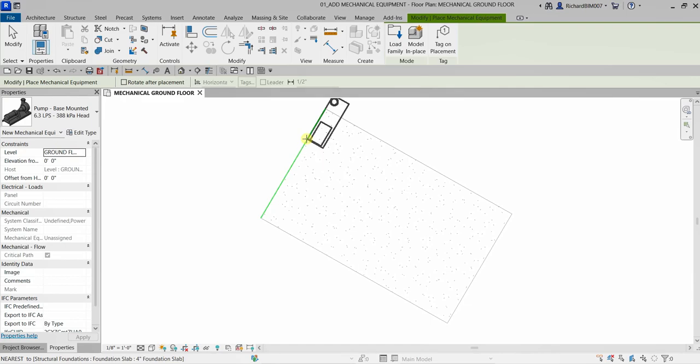So you will notice every time you press spacebar, it follows the position of that slab, the angle, the alignment there. So every time you press spacebar, it rotates 90 degrees by 90. Okay, so that's how you do it, and then you can now place it here.